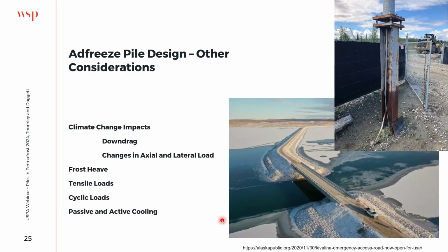Tensile loads are another one. So evaluating tensile loads, obviously you would not include your end-bearing component, but you'd be looking at the tensile skin friction and potentially a reduced factor on that as well. Cyclic loads are not as common anymore as they have been in the past due to machine damping and other things, but cyclic loads are also one that will change drastically the behavior of your pile performance over time.